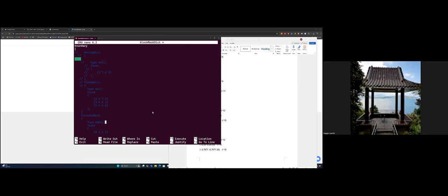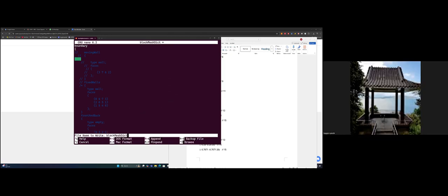So this should be it, and we can save and exit. Why does it have to be higher? Because the z direction is the length of the pipe, and we said it's 20 meters. So you need more elements along the length of the pipe. Even the 100 might not be enough, but for now, let's just test this case.